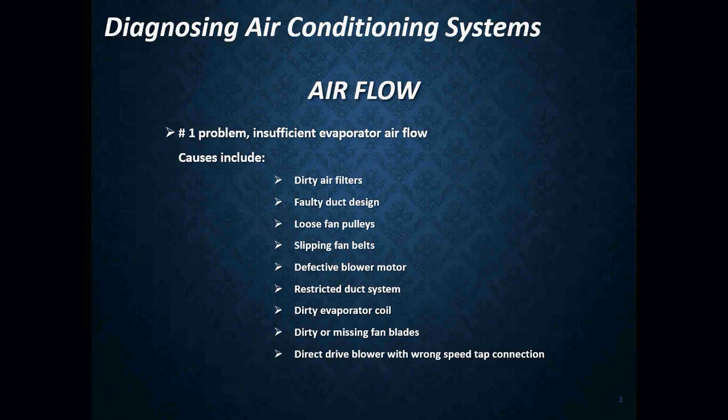Now, assuming that the entire air conditioning system, or AC system as we usually call it for short, was originally set up properly, which means somebody came in there, did an air balance test, and made sure that we had the correct amount of CFMs coming out of each supply duct and our return ducts, too much air probably will not usually be a problem area, right? Because it's set up correctly.